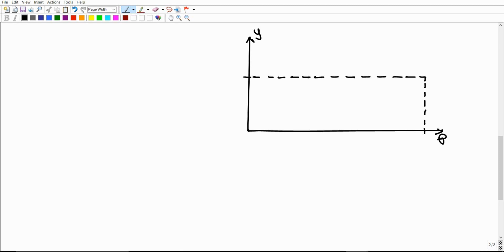In the first period, which is 150 degrees, we have to do rise with simple harmonic motion. So you have to measure the 150 over the theta axis. If you divide 150 by 30 degrees, this gives us 5. It means that your objective is just to measure 5 centimeters. Remember that every 30 degrees is equivalent to 1 centimeter in our scale. So I'm just gonna measure 5 centimeters over the theta axis, starting from the 0 point, and we're gonna end up with this point here. So this is gonna be the 5 centimeter point.